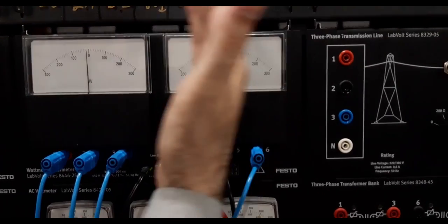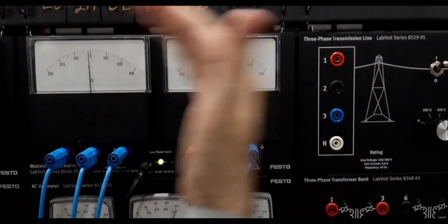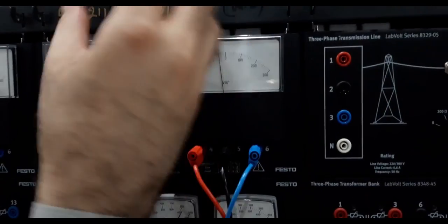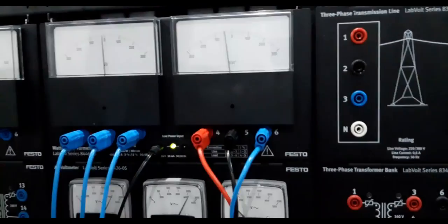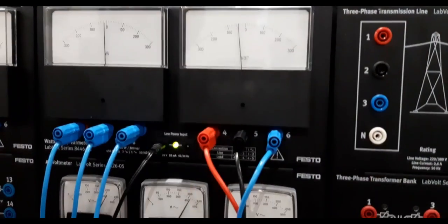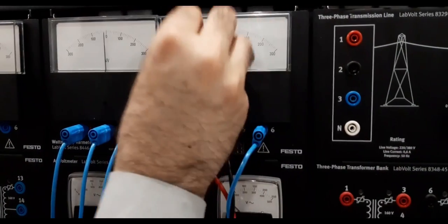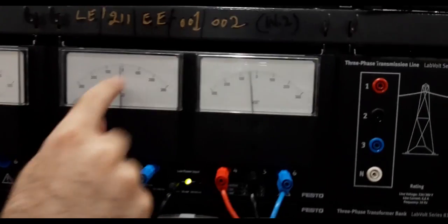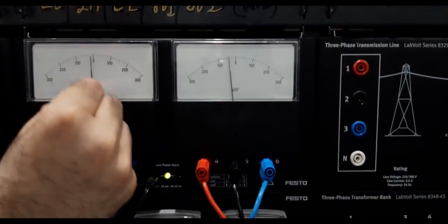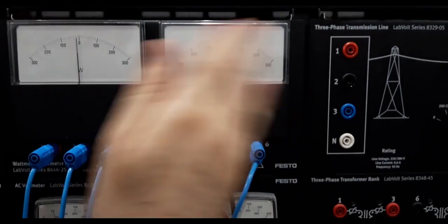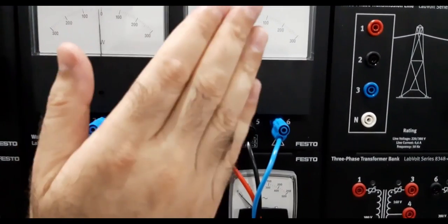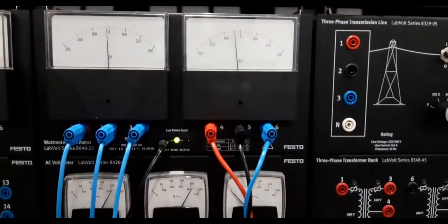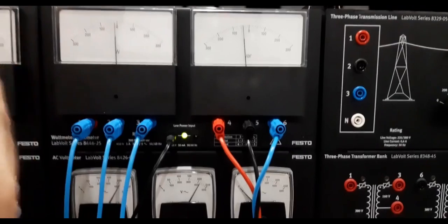And if I further increase the field current, you will see that the reactive power now moves in the other direction, or it becomes positive, meaning to say that now the induced EMF is more. It is overexcited case as we have increased the field current. So now this synchronous generator provides reactive power to the system. And one can see here, there is slight active power that is positive. Because by changing excitation, the active power should not change. This must be in the other direction, meaning to say that a generator should provide active power to the system.